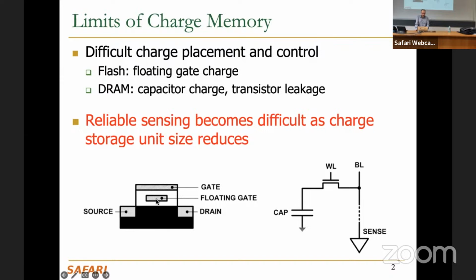It's not as fast as in DRAM. So in DRAM, you need frequent refresh. But in flash memory also, you need to do refresh at some point. If you, for example, store data in your flash memory and don't touch it for a few years, it's very unlikely that you can recover your data nicely. There might be some data that you cannot recover at all.